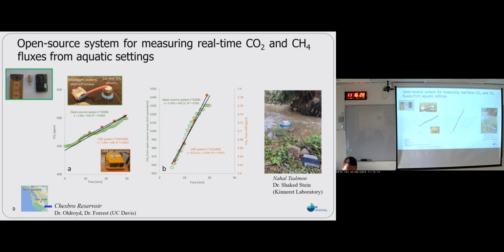So you can see this is the chamber. This is the CO2 sensor. This is a fan just to circulate the air. The reason we have this funny tube is just to make it float, of course. And this is the data logging unit with a small solar panel. You can see this is a modem, so everything is being recorded and transmitted online. An SD card to back up the data, a battery, and so on.